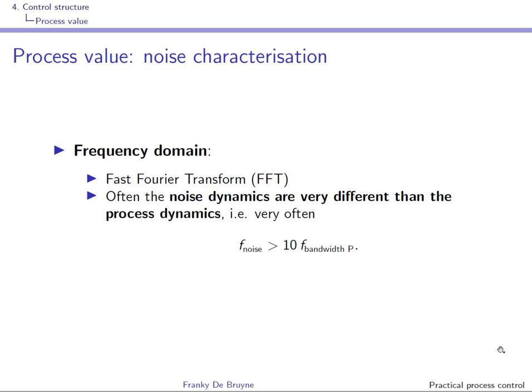You can of course characterize the noise in the frequency domain, and therefore you can use your best friend from the course of signals and systems, the fast Fourier transform, or FFT. You will see that in practice the noise dynamics are very different than the process dynamics, and typically the noise content will lie more than a decade above the bandwidth of the system.